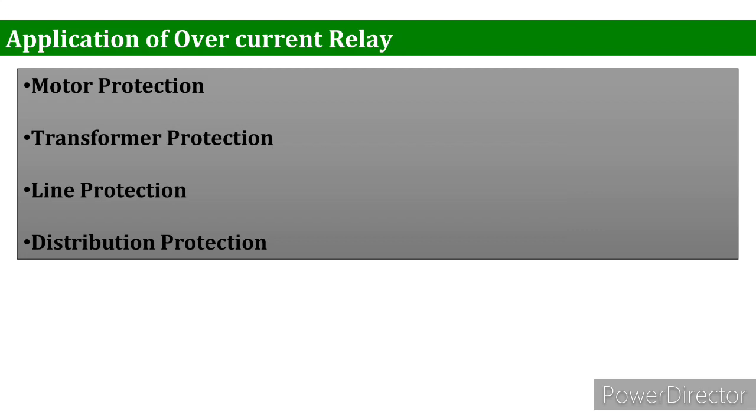Very often, the relays do not need to be directional, hence no PT or potential transformer supply is required. It is possible to use a set of two overcurrent relays for protection against interphase faults and a separate overcurrent relay for ground faults.